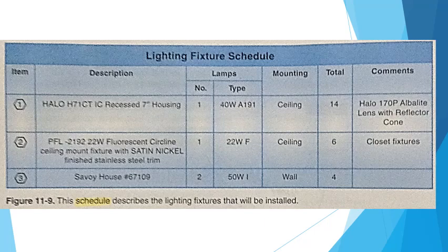Equipment schedule. An equipment schedule lists the large electrical equipment being installed. The information provided in this schedule varies depending on the specific type of equipment listed. Equipment schedules may include the voltage provided to the equipment, size and type of overcurrent protection, and the number and sizes of conductors feeding the equipment. Motors, heating units, and cooling units are often listed in the equipment schedules.